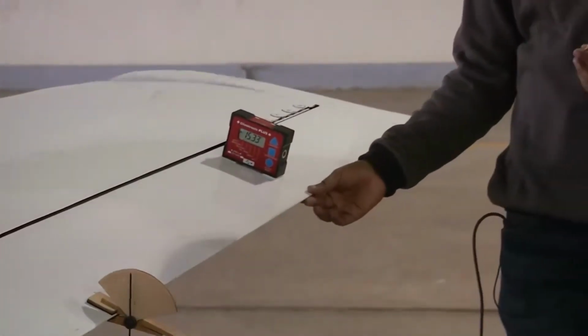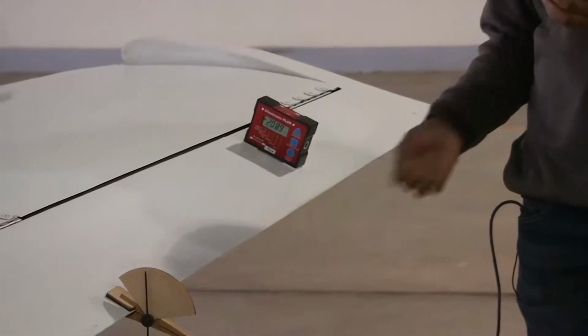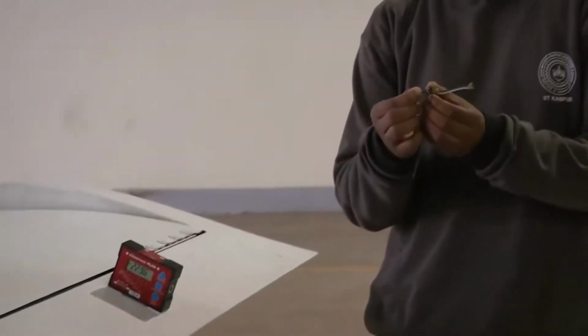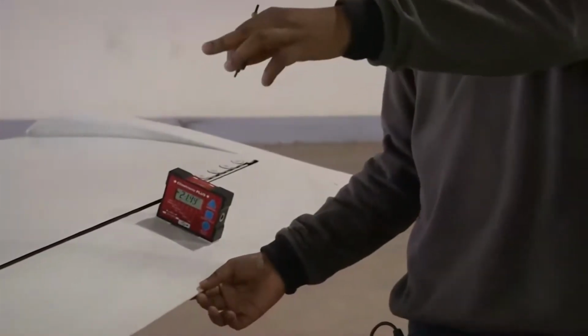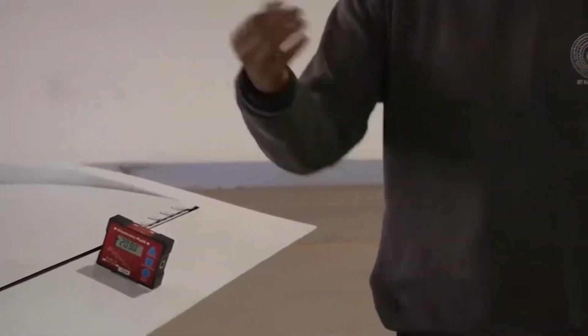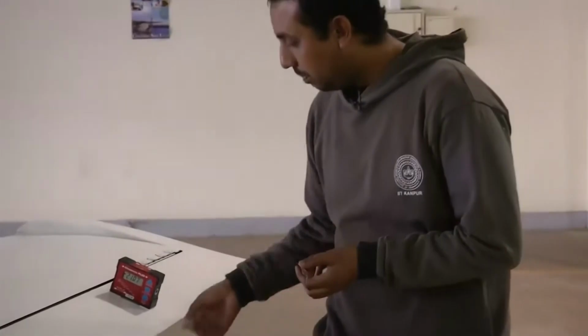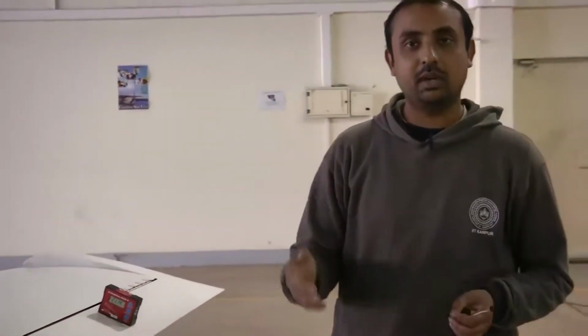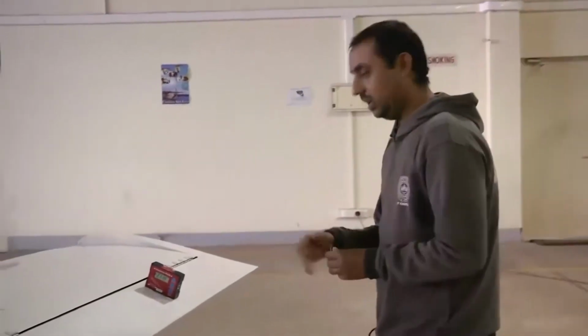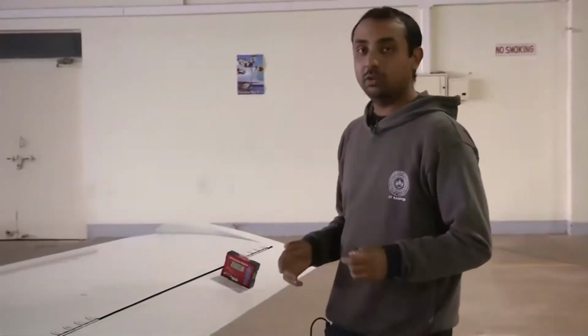As you will deflect this control surface, it will act as a rotating switch, and corresponding to that rotating switch, a voltage will be shown in your LabVIEW software on that particular angle, and then that particular value of voltage you can calibrate or map on your linear scale. So, we will be showing you how that experiment is performed.